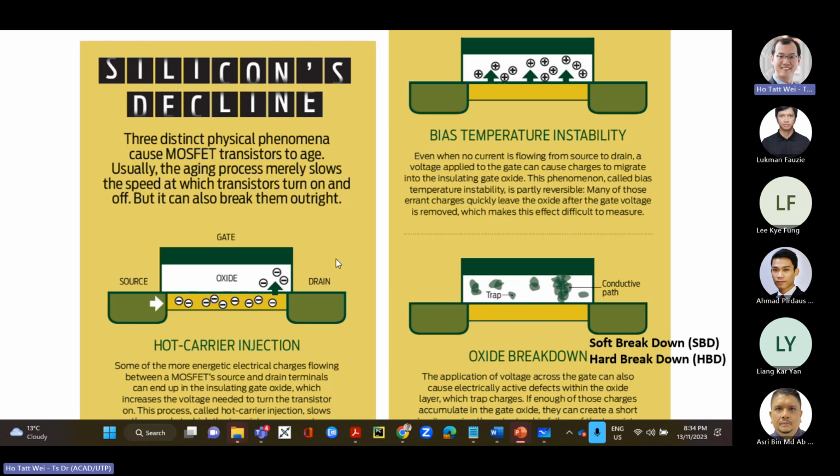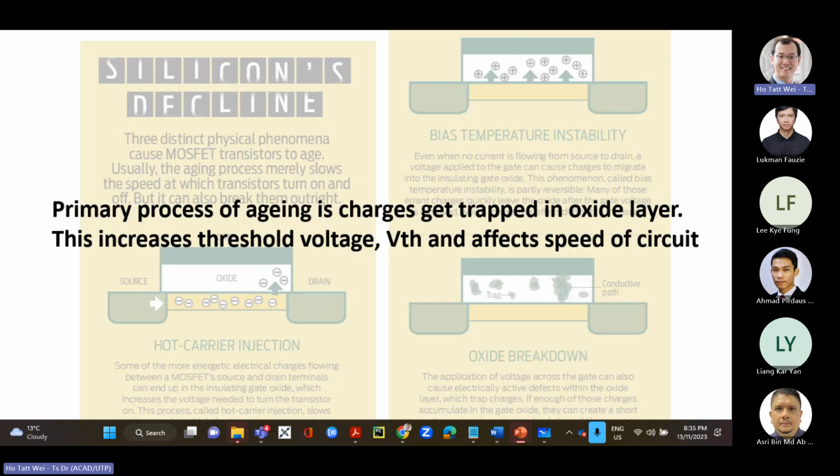You can actually model and quantify the delay. You can have an estimate of how much the delay will increase over time, depending on a few properties. And that's what we're going to look at, the factors that make this worse or better in different transistors. Because what we care about is actually the factors. Of course, if you can calculate a numerical number, it'd be good, but I wouldn't trust the numerical number too much. It's just a ballpark estimate. The key point is comparing in terms of the factors. But for your exam, for your tests, I will get you to also be able to estimate the numerical factors.